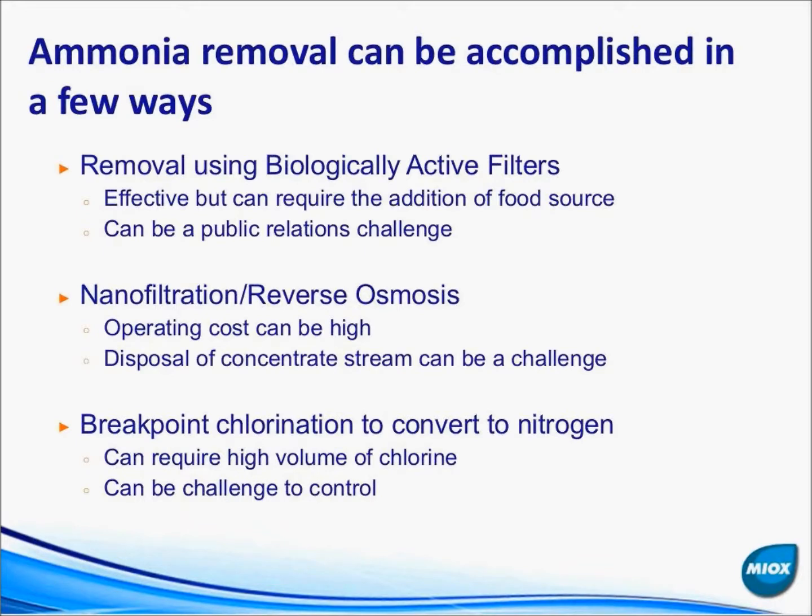I know that in the Midwest here, where in my former career I actually did a couple of these projects, we would run into some real issues in the winter when the temperature would drop significantly and there wasn't a significant food source, and it was very difficult to keep those bacteria alive and active until the next year. And so some plants actually have to dose things like methanol as a food source in order to keep those organisms alive. And so that can be very, very challenging and expensive to do.